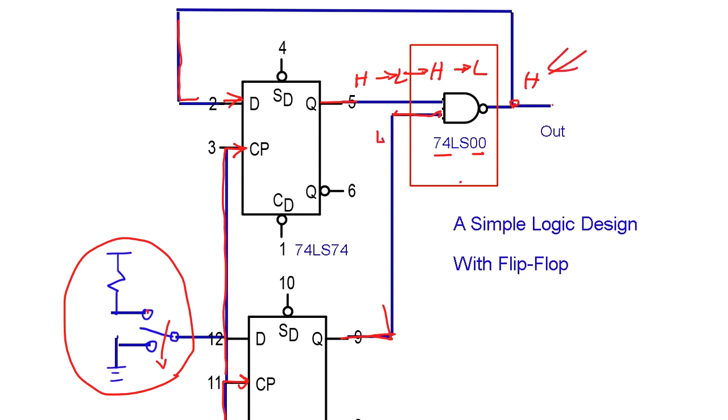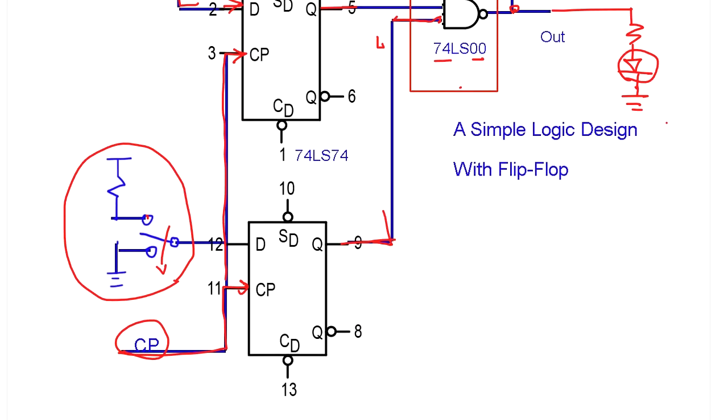Okay, so we put the LED and observe. So for the clock, if you use a digital clock, it's too fast and you cannot see this transition of the logic. So we use one made by a 555 timer, which generates a very slow single pulse.